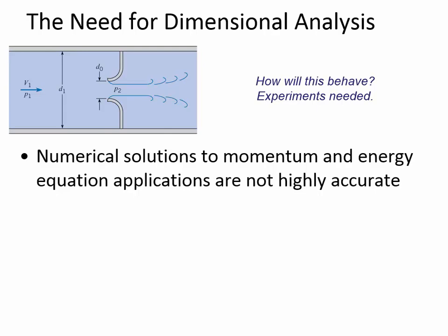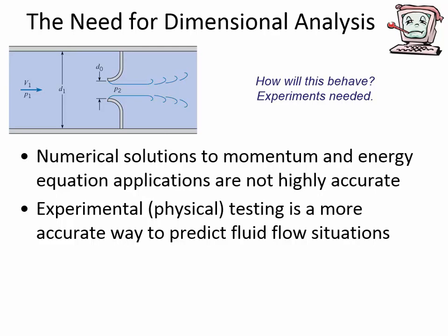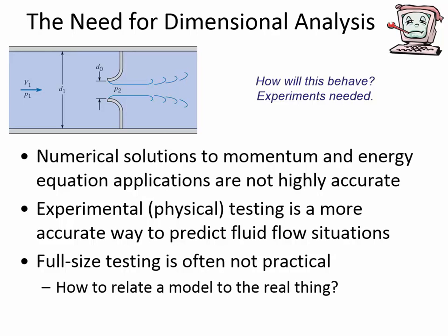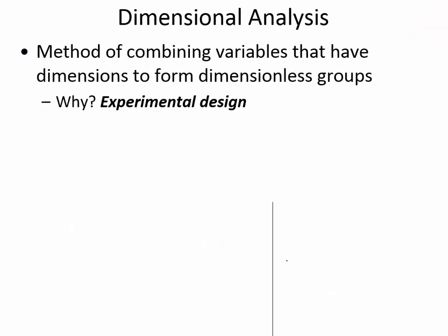Well, we can use the same numerical models, like I showed you that spillway model. We can use those numerical models to simulate what happens inside of there. But sometimes they are not really accurate unless they've encountered and have been programmed and calibrated to a situation like this. You can't assume a computer is always going to give you an accurate result. And so you have to verify that with physical testing. And you can't always do full-size testing, so it's the small-scale models that are used.